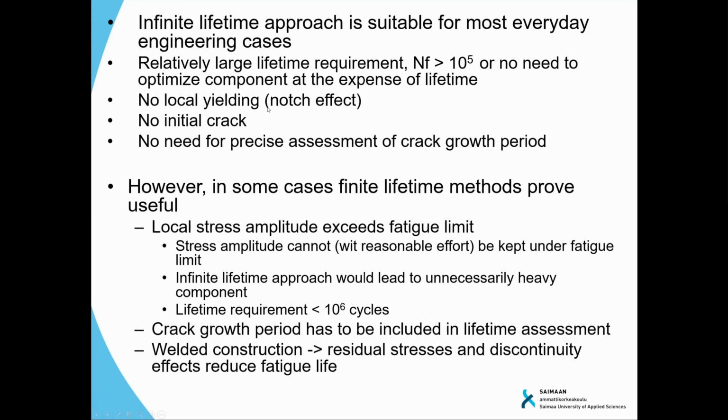This means that even though we would have a nominal stress below the yield point, if we have some notch that will increase the stress in that location above the yield limit, it means that we cannot apply the infinite lifetime method. So we just need to check whether it works or not. Yes, exactly. Okay, great.